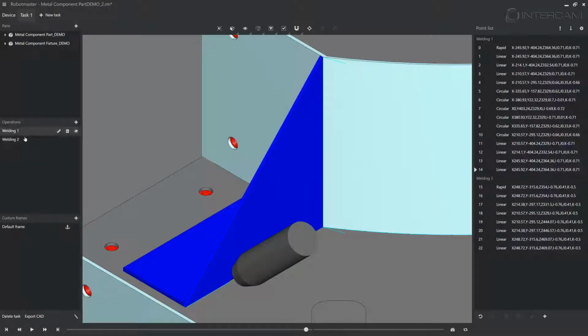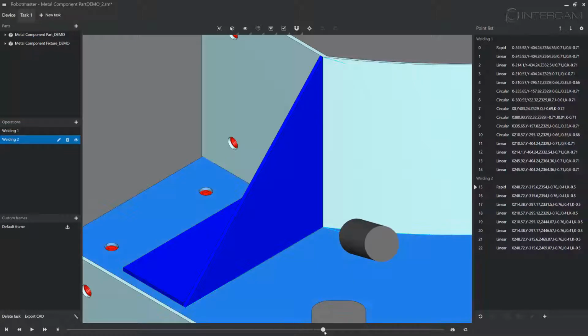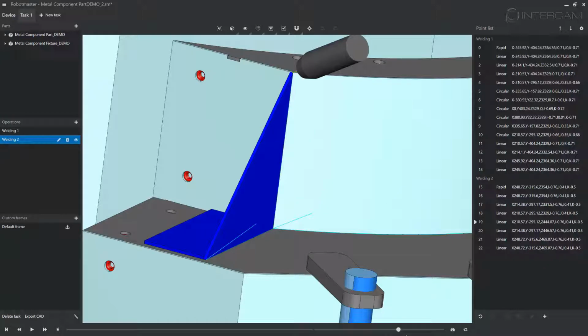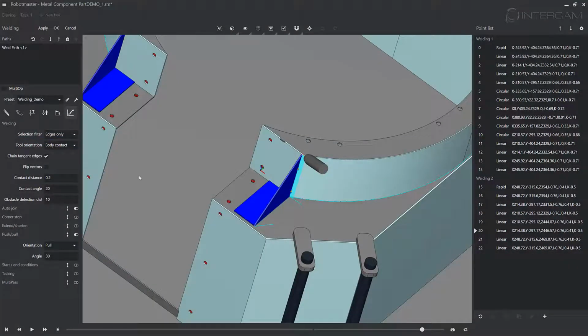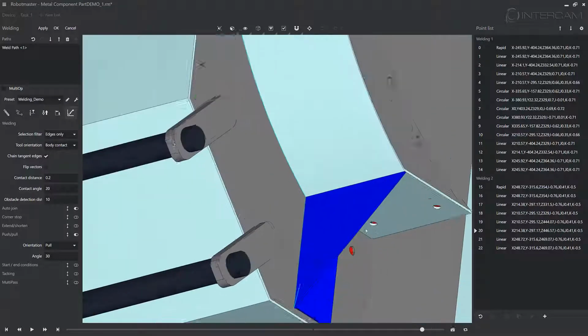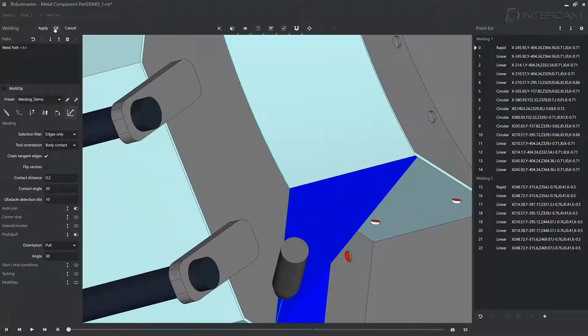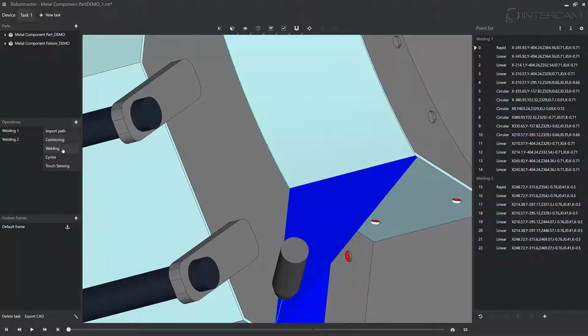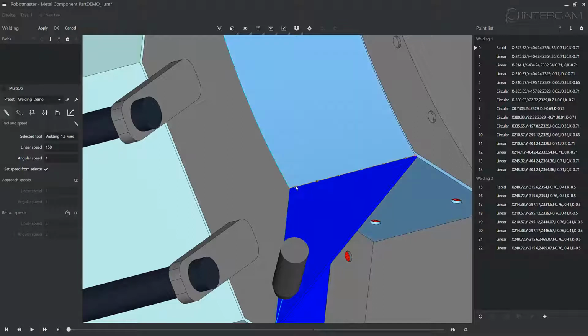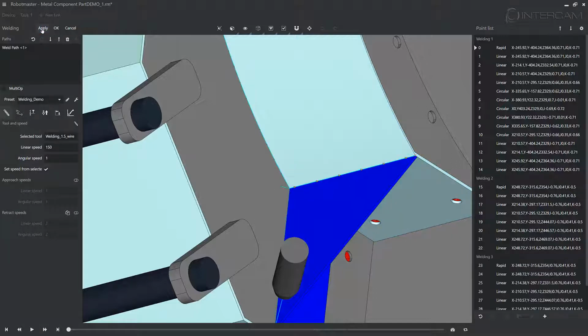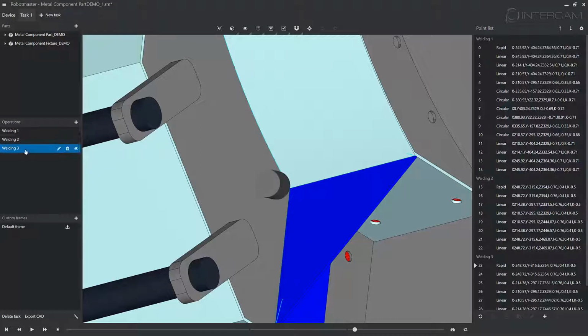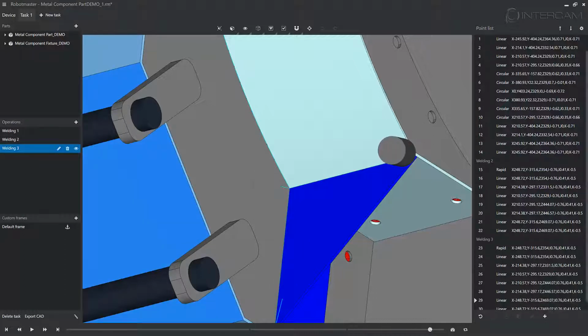When selecting the right vertical, Robot Master will immediately detect and indicate the weld and the vectors as you move your cursor over the coincident end of the desired weld line. When you see what you want, you click to confirm. Once everything is perfect, you apply the optimal welding path and OK the operation. Once the right side is finished, we will repeat it on the left vertical.